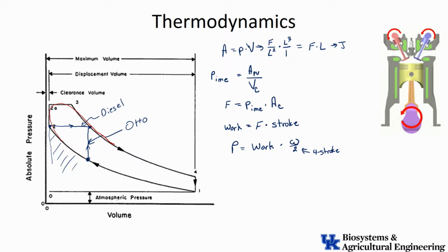Okay. Now the other thing that we don't see, that we forget about, again, this is a 4-stroke engine. So down on the bottom here, there is a line, that horizontal line that goes back and forth, and we often ignore that. Remember, 4 strokes. We look at the curve up here, the lower curve on the PV loop. That is the compression stroke. Then we have the power stroke coming back down, but now we have to have the exhaust stroke. And so that's where we would come out across this line like that for the exhaust, and then we have the intake, and we would come back the other way for the intake, so we would actually suck it in.